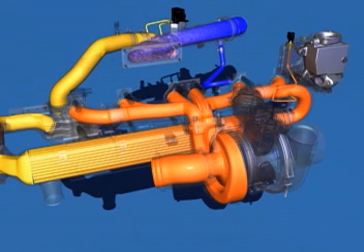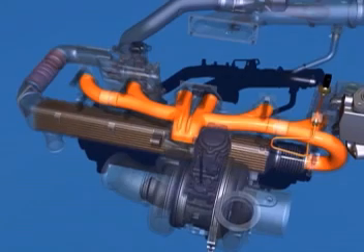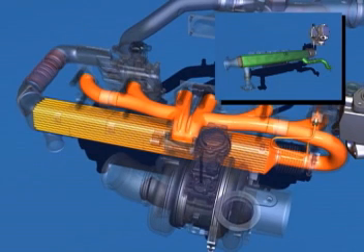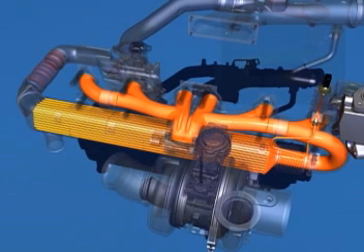The coolant and EGR gases enter the cooler on the same end of the cooler and flow parallel to each other. As the gas enters the cooler, a diffuser ensures even distribution. The even distribution is the only way to achieve the necessary cooling of the gas.